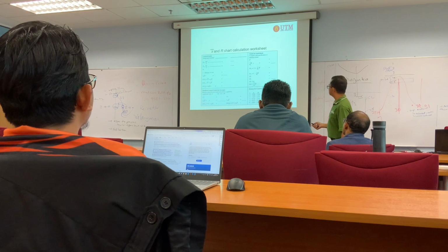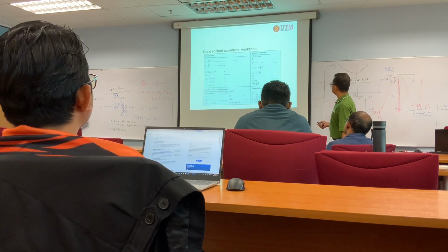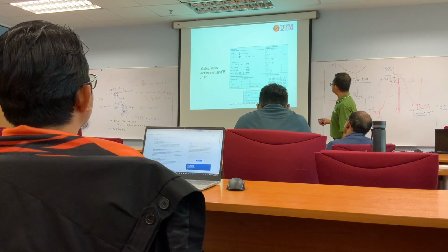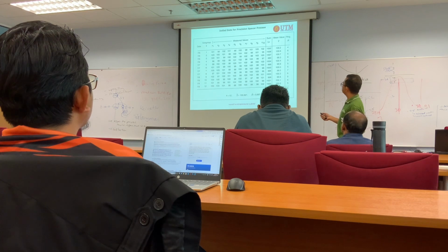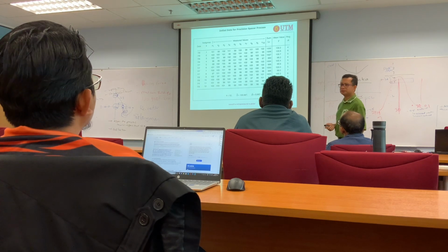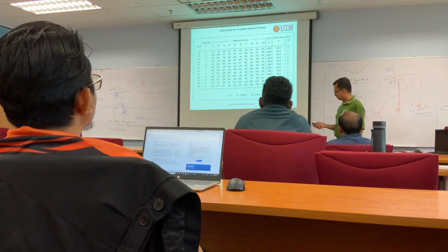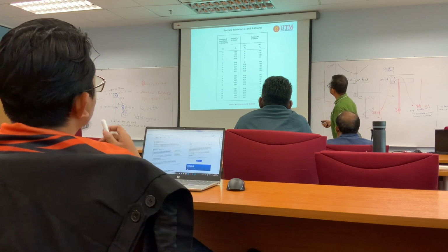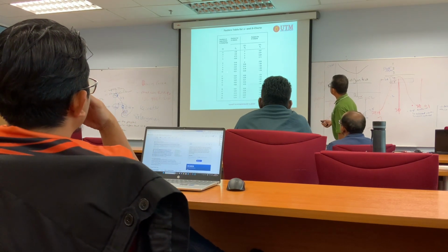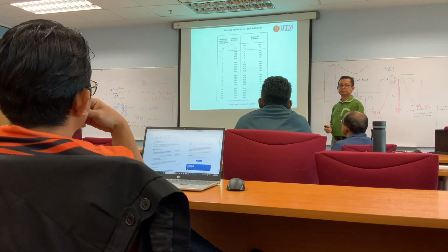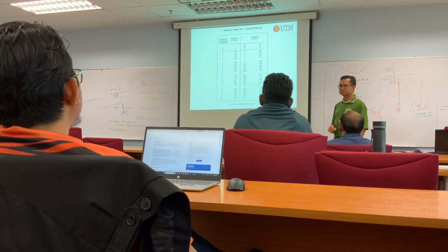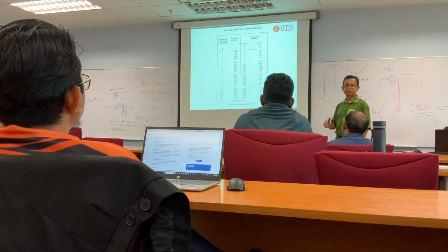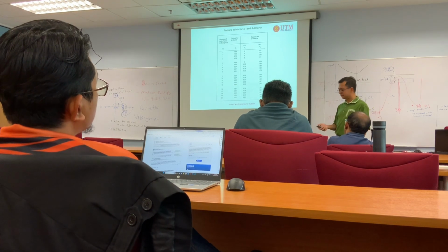So I would like to share with you, because in this case we have only 4 samples for each subgroup. But how about for this case we have 10 samples for each subgroup? As engineers, no problem if we use X bar. But statisticians, they are not happy with this, because they said if we have large n, we should use the standard deviation chart. But we forget about that. That's the, what you call it, school of thought. Statisticians like accurate things, but we don't mind, as long as we got the result.